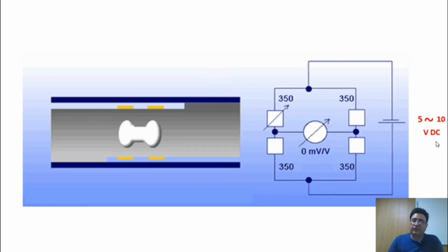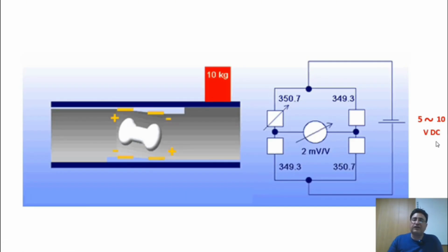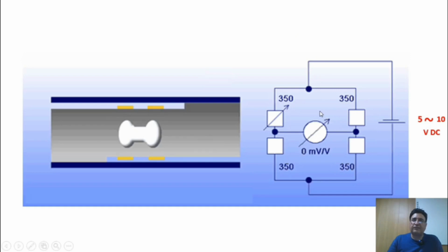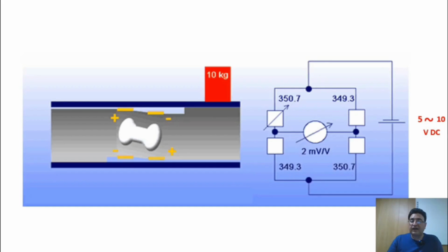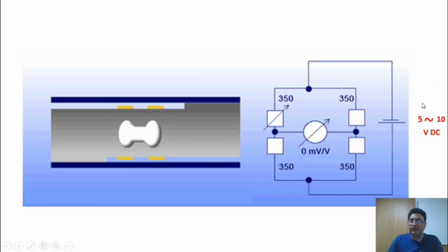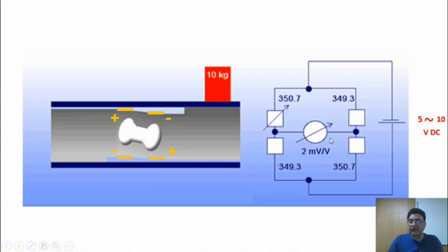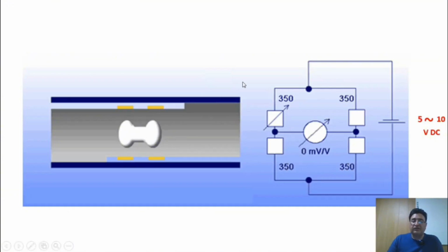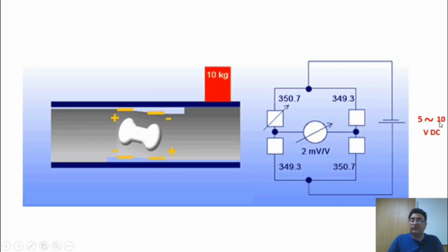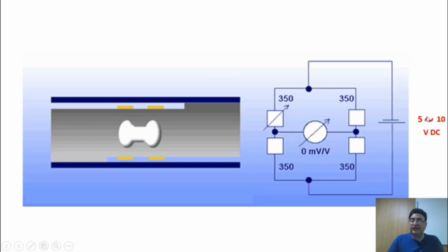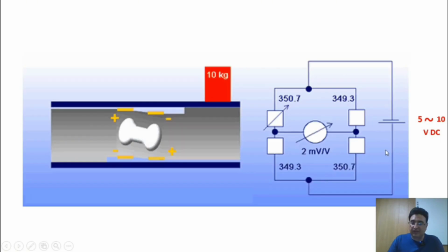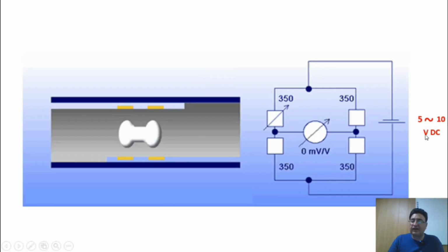Of course, let me point out that when we connect the load cell to the weight display, there's no need for us to connect a separate power supply to it ourselves. In other words, the load cell gets this voltage from the weight display. So, for this load cell circuit to be activated and start working, it needs a voltage between 5 to 10 volts DC. When we connect the load cell to the weight display, it receives this voltage from the weight display.